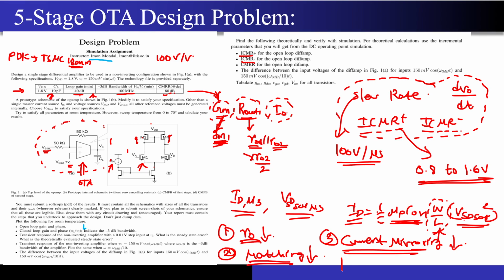What is the good channel length? Maybe 3 to 4 times the minimum channel length, correct? Since this is 180 nanometer, I can choose 540 nanometer as the channel length for my transistors. Correct? So this is the overview that I am giving you right now. We will solve the problem. Don't worry. I am just trying to tell from where the specs will be coming.